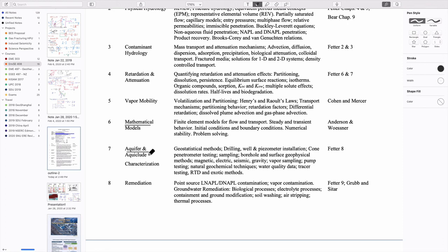So now hopefully we understand something about the physics of free phase flow in porous media, the mechanisms by which stuff gets dissolved and gets carried by diffusion and advection, what the controls are, what happens when that is either conservative or non-conservative in the groundwater zone, and how that also applies above that in the vadose zone. So we've got all the mechanical tools, in terms of the physical understanding of what's going on, to be able to make a stab at remediation methods.